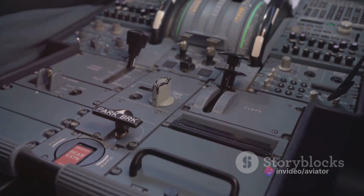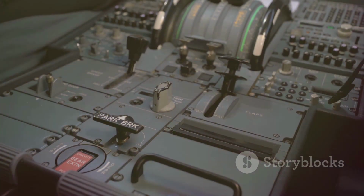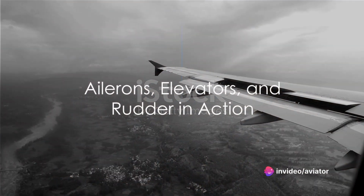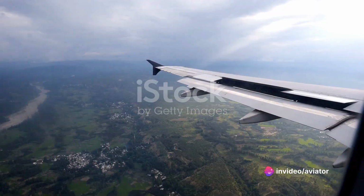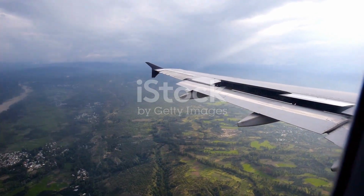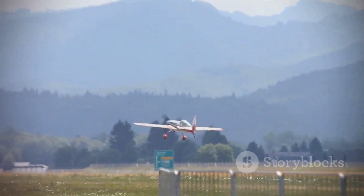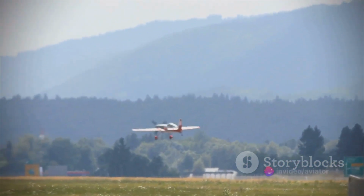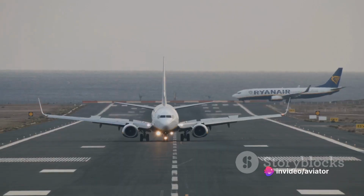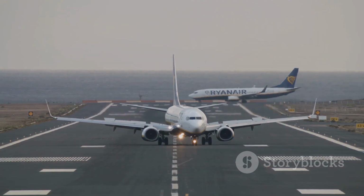These are the primary controls, but how do they actually change the aircraft's direction? Well, that's a story for our next scene. Let's dive deeper into how these control surfaces work. First off, we have the ailerons located on the outer rear edge of each wing. When a pilot turns the yoke left or right, the ailerons respond by moving in opposite directions. If the left aileron is raised, the right one is lowered, and vice versa. This creates a difference in lift between the wings, which induces roll, allowing the aircraft to bank and turn.